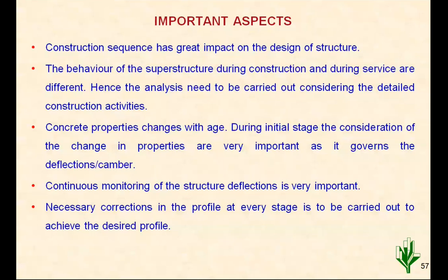Then another important aspect is concrete property. With respect to age, concrete exhibits different properties. It goes on achieving strength. Also, it develops elasticity more during the initial stages. After, say, 28 days, more or less the strength will remain constant, E value also, but there is a creep factor which changes the deformation of the structure. So it redistributes the entire scenario. So that has to be properly modeled.